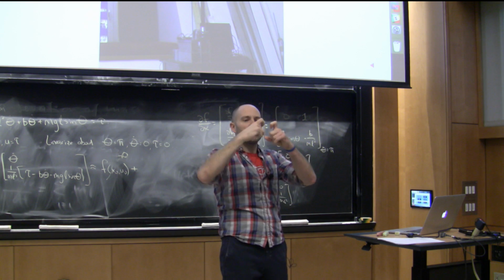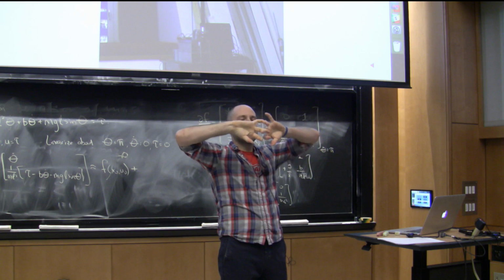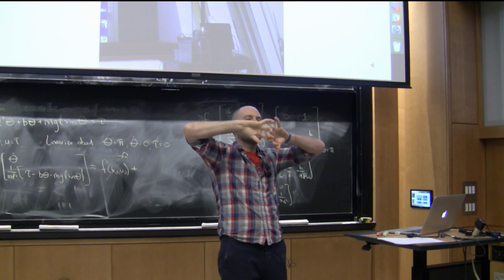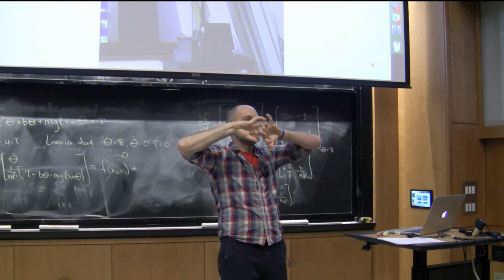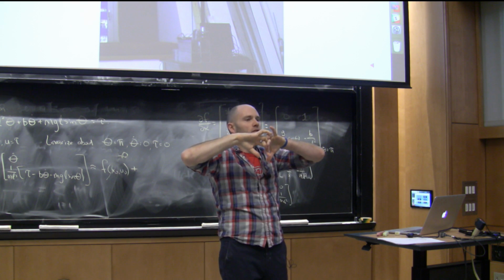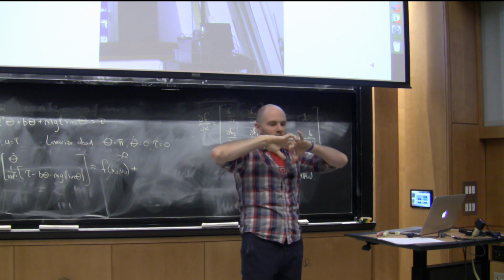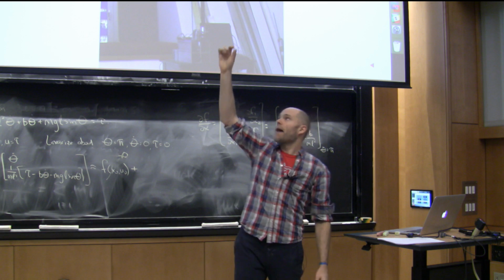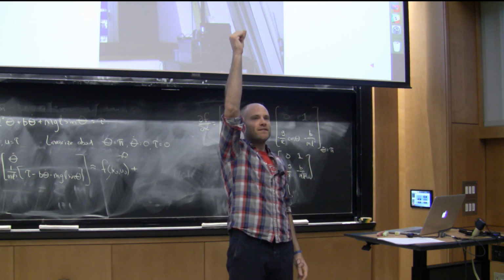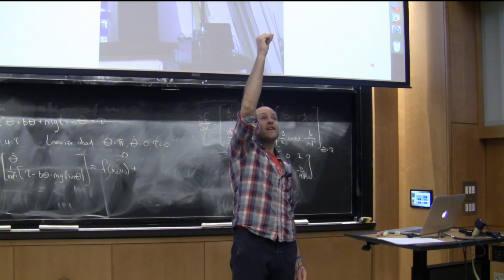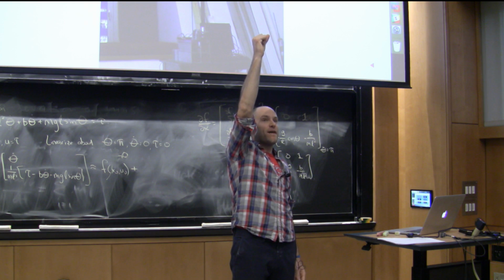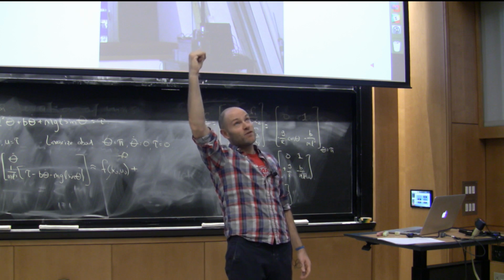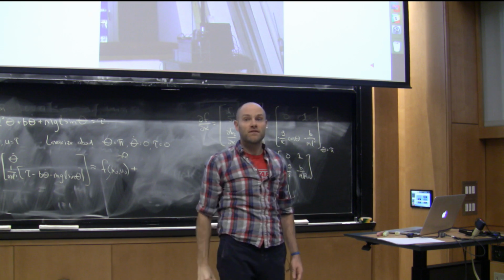The standard way to think about that is if I have some gears with teeth that are pushing this way, and then I change direction, it takes time until I push to the other side of the teeth to see it, okay? So gears have that a lot, but other transmissions tend to have it too. If you change directions, it takes some time. So as soon as you're at the top, you'd like to be commanding 0, okay? And then you start sliding just a little bit, and it takes some effort to push, and then it kind of kicks yourself back up. And it takes a little bit more effort, kick, you end up going back and forth.